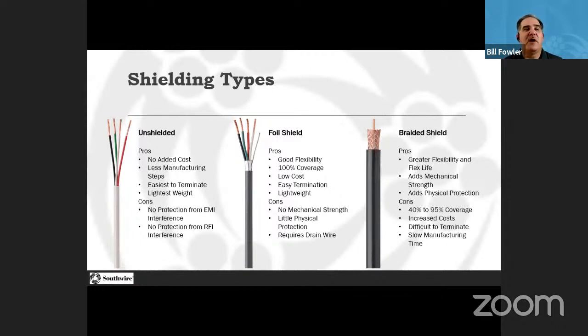You have to peel that braid back, trim it to a certain distance, to put like F connectors on, different type connectors. So it's like trimming really fine hairs. You got to make sure that you cut them all so you don't get one in with that center dielectric in there, so it can cause interference.